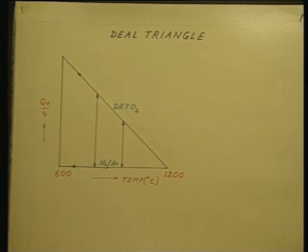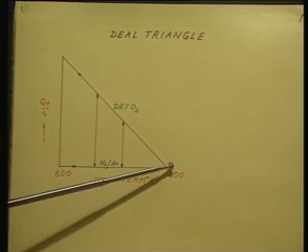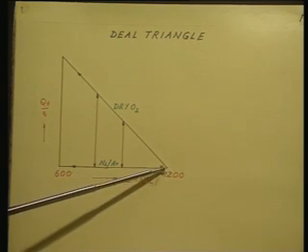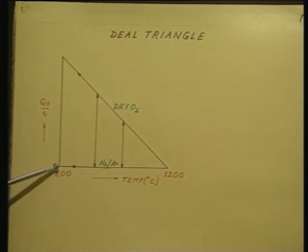So, in this inert ambient oxidation is entirely stopped, oxidation is not taking place, therefore, there is no question of incomplete oxidation. Whatever oxidation took place at very high temperature, and at that high temperature, since oxidation rates were much faster, there was much less chance of having incomplete oxidation. So, then one follows this baseline and you end up with a much lower fixed oxide charge. So, this is the standard practice today.